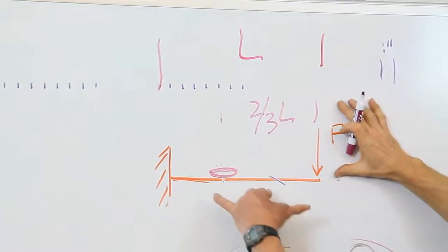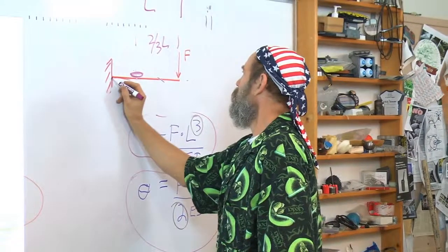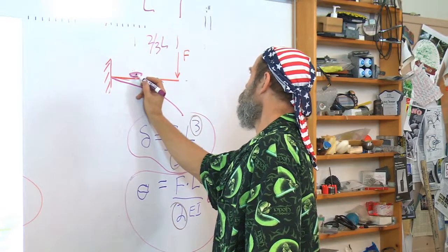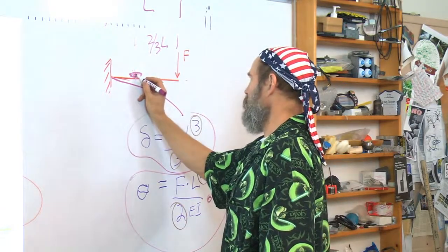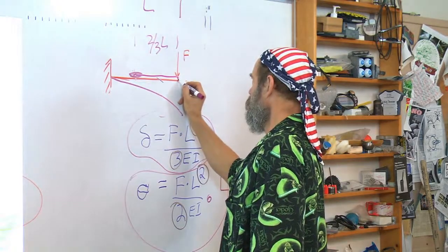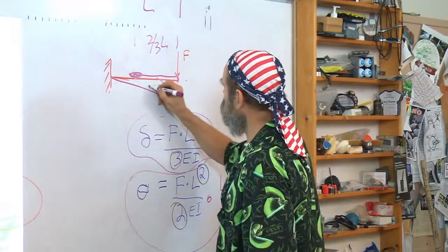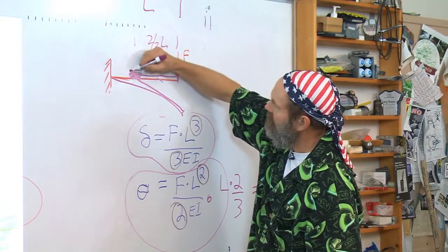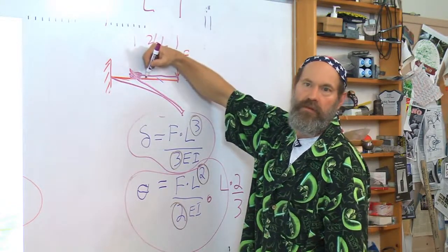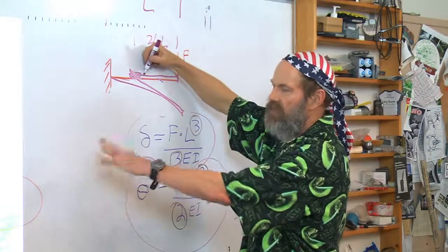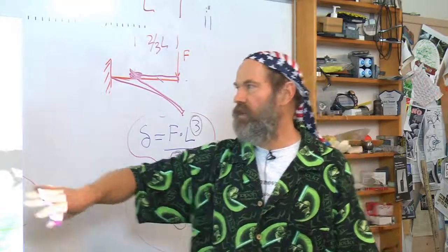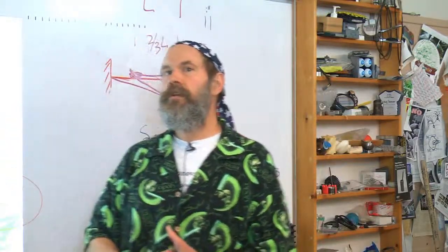And when you push on this beam with a force F, any force F, it bends. And remember, it's not mounted to the beam, it's mounted to an arm on the beam. This arm on the beam will deflect up, and the lens will stay put, but it will tilt perfectly. So here's how you can use something you may say, man, that's a problem, to your benefit here and here, and avoid the problem, for example, in measurement.